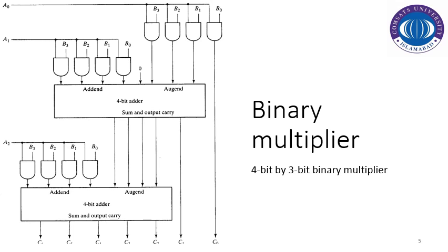So in order to avoid complexity, these interconnections are not shown. The first partial product is A0 multiplied with B0, B1, B2 and B3. The second partial product is A1 multiplied by B0, B1, B2 and B3, and the resultant two partial products are then added. The first multiplication result is A0 B1 that we have achieved directly. As far as the second and third are concerned, the second partial product is the multiplication result of A0 B1 added with A1 B0. So that is our second product term, and similarly for the third and fourth product terms,